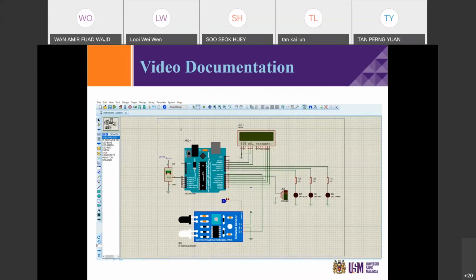When the logic state of the test pin is turned to 1, the sensor will start to detect the temperature and send the data to the microprocessor to transfer and calculate data, and the data is sent again to the LCD display. The LCD display will show the result of the temperature value detected by the temperature sensor. When the body temperature detected is lower than normal body temperature, which is 37.6 degrees, only the green LED will light, showing that the person is in normal condition.